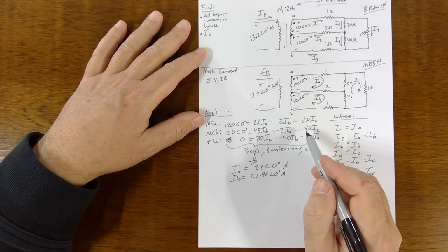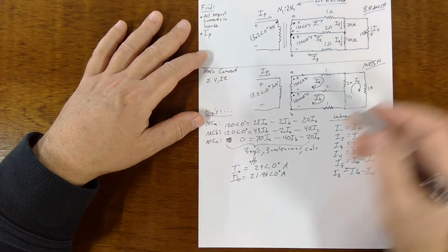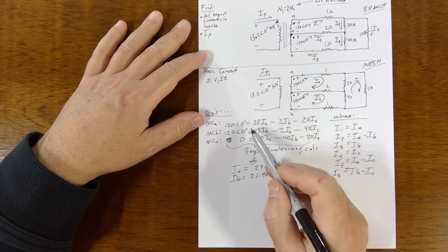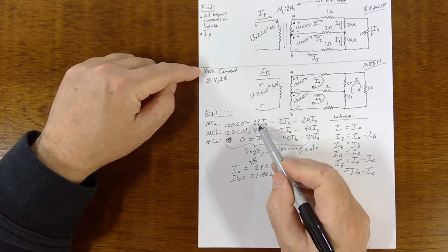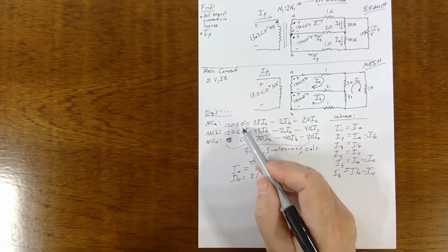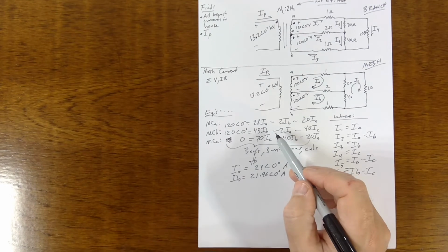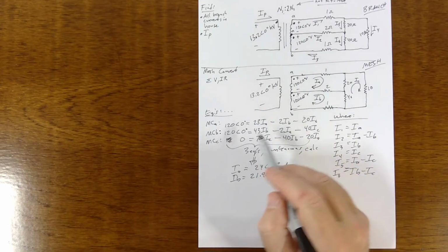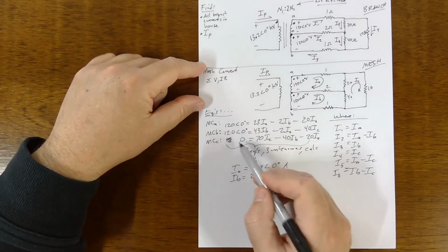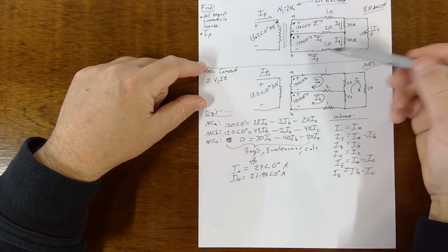As phasors, the J components are all going to be 0. Actually, because the angles are 0, you could get away with doing this as scalars. Yeah, that would work. You could just forget the angle 0 part, and it should work fine, because everything's 0 here.